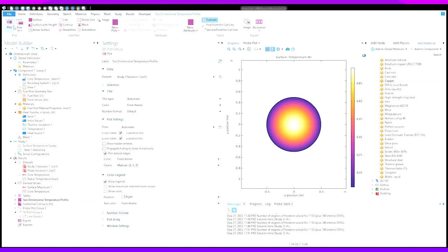Alrighty, so that produces this plot, and you'll notice both from the model we built and just by looking at this that the temperature only really varies with the distance from the center. It's only radially dependent. So we could simplify our data and make it much easier to analyze if we could do a one-dimensional plot. However, with the model wizard, we told COMSOL, I want you to think in 2D, so it doesn't immediately show the option for a 1D plot.